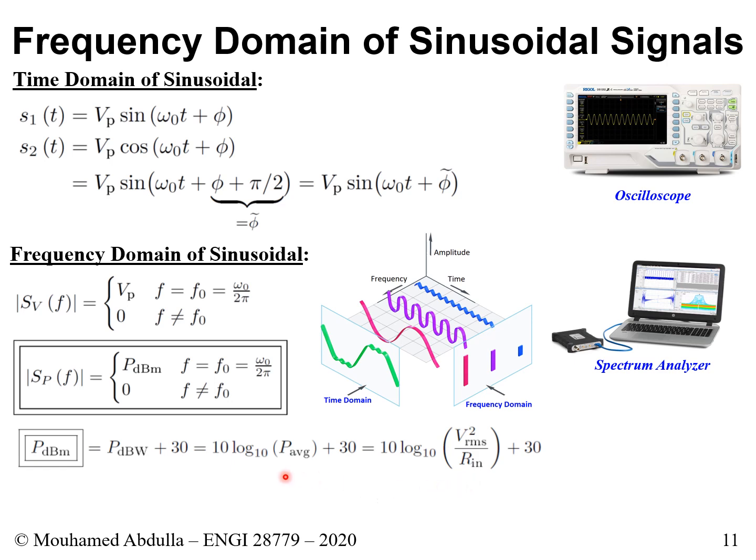Okay, so now we replace the P average with this. Next, we could maybe replace the V RMS. What is the RMS of a sinusoidal? Well, we said the RMS voltage of a sinusoidal is equal to the V peak, or the amplitude, divided by square root of 2. So you put that, you square it, it becomes V peak squared divided by 2, our input. And this is what we get so far.